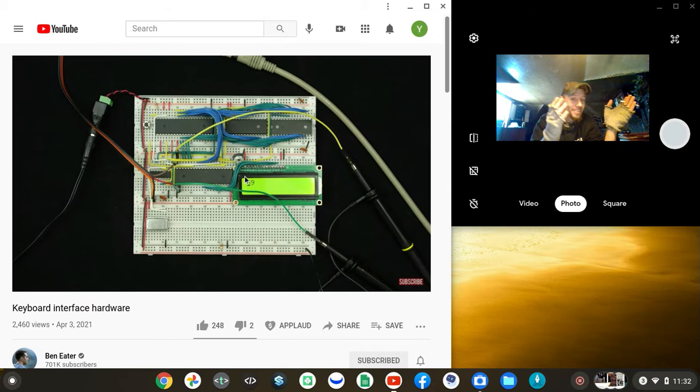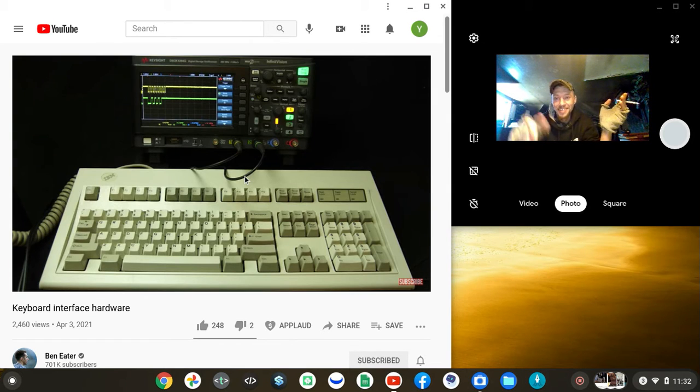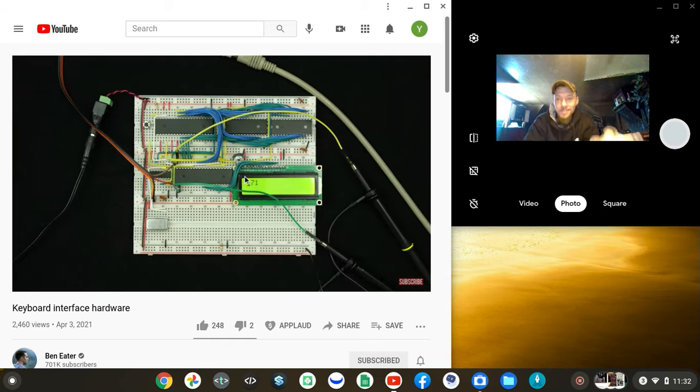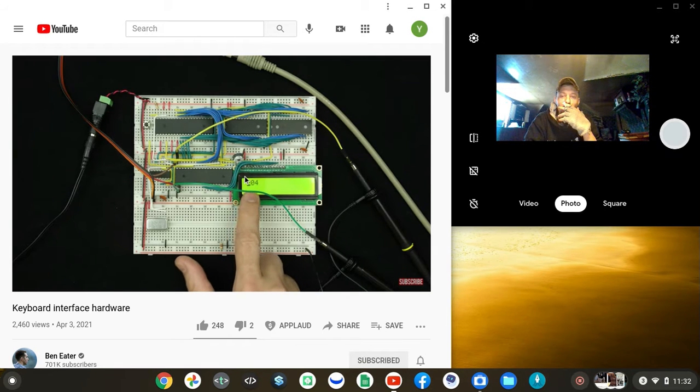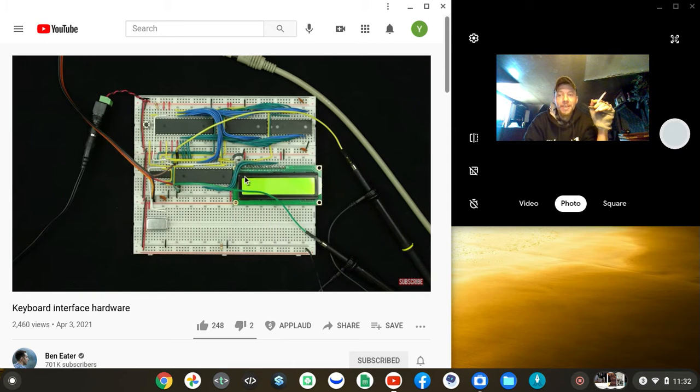So we're seeing something, and there we go. We also see the data on the scope. And if I press a key, you see the data for that, but you also see the counter increment. And the counter should increment every time there's a clock pulse. If we reset this, if I press a key...